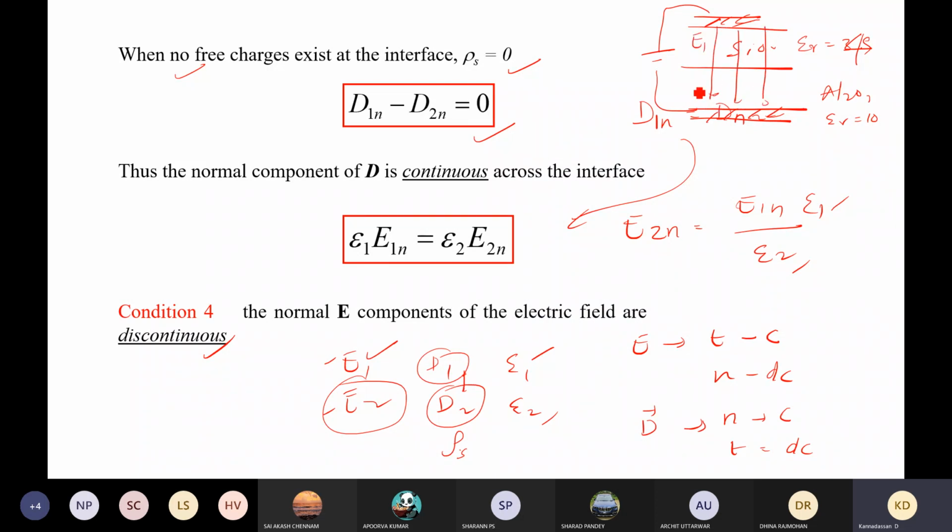Of course, we know that here electric field 1, here electric field 2. According to this, the normal components alone will be available. We know that the normal components are not the same. In that case, to make this entire system stable, some surface charges will be accumulated naturally. So because of that, if you keep on increasing the electric field, the capacitor value will suddenly increase, and after breakdown it will start to discharge. This behavior you can find in many capacitors, particularly this kind of sandwiched materials. And this kind of accumulation of charges is often referred to as Maxwell-Wagner polarization.